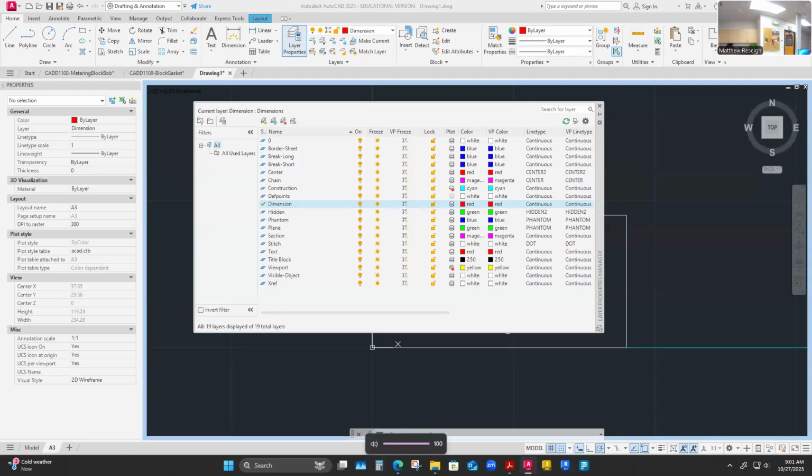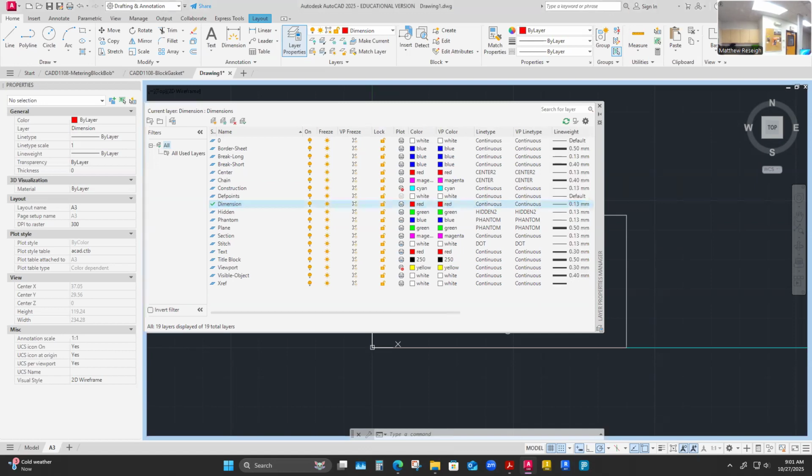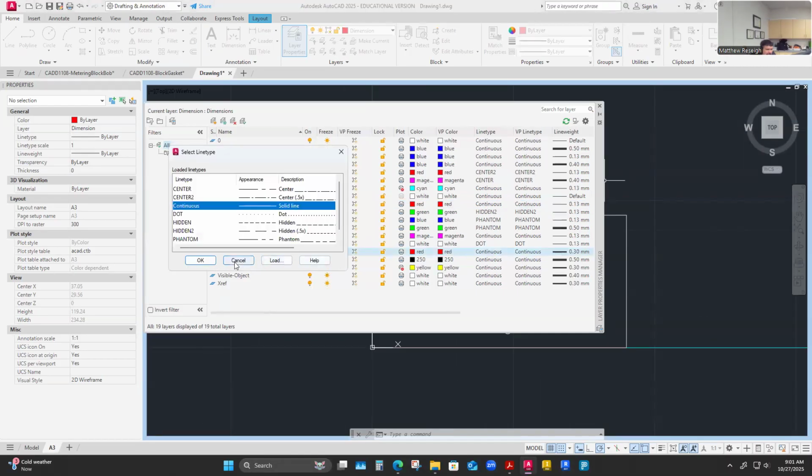Yes. I'm going to continue on. All I was doing while I was in here was just looking at my line weight. And so to do my axes, I'm using a light line weight. So I could choose anything that's continuous and light line weight that would also plot. For me, the dimension layer works well for that. It's a 0.13 millimeter line weight. It's a continuous line, so that's a good one. I mean, the text one's a 0.3, so it's a little bit heavier.